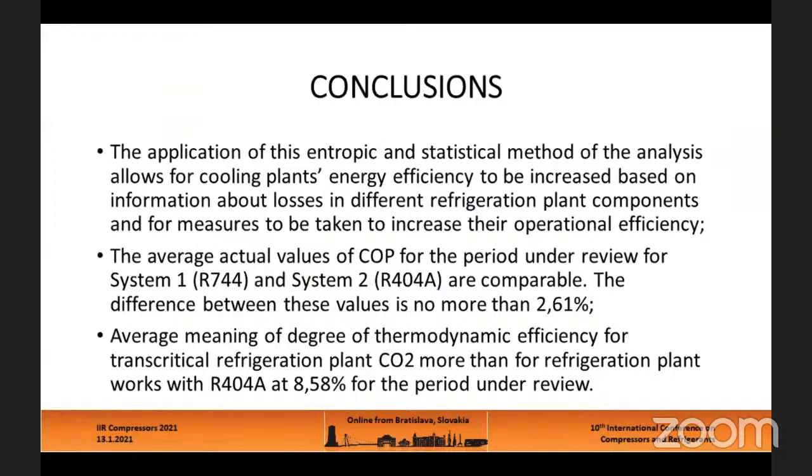Some conclusions. The application of this entropic and statistical method of analysis allows cooling plants' energy efficiency to be increased, based on information about losses in different refrigeration plant components and on measures to be taken to increase operational efficiency. The average actual value of COP for the period under review for System 1, CO2, and System 2, R404A, are comparable.